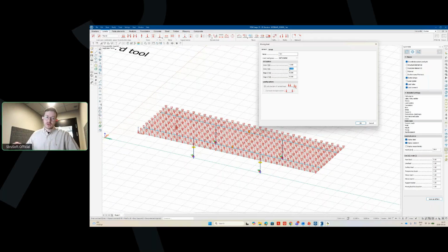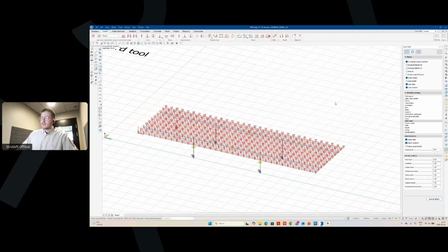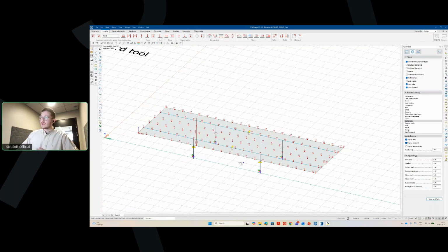And here you can affect your calculation times quite a bit. So what I will do is I will increase the distance between the nodes in Y direction. I can, for example, increase this to 1.5 meters. And then you can see what happens. It reduces the number of cases quite a bit. This does mean that we will get a bit more inaccurate results, you could say, or we will not evaluate load positions in as many positions. But let's keep this for now,